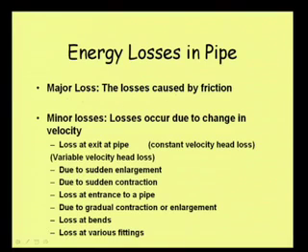Okay. Then, as I have explained, the energy loss we can divide into 2 parts, that is the loss caused by the friction, and then there are some minor losses. And of course, this major loss has one characteristic: this loss is due to constant velocity. When the water is flowing in a pipe, there is no change of velocity, still there we find that head loss is occurring. So, this sort of loss is also called constant velocity loss, constant velocity head loss.